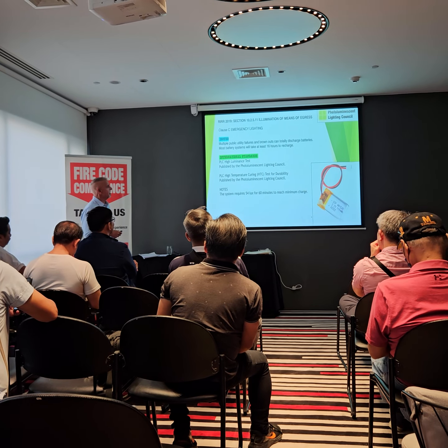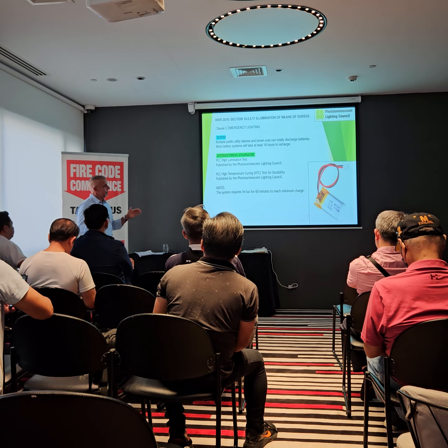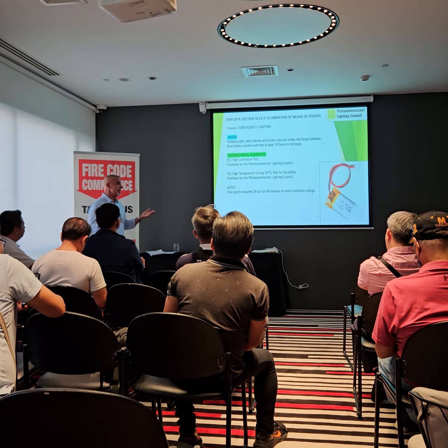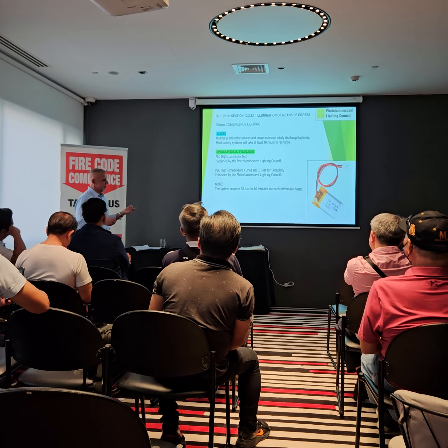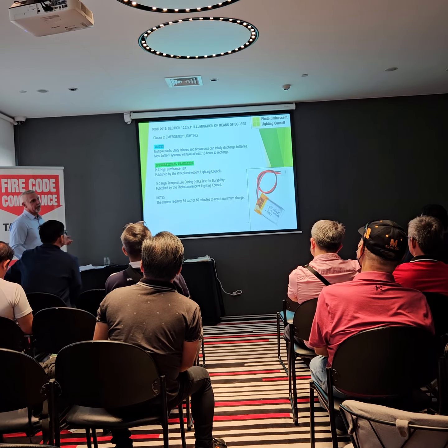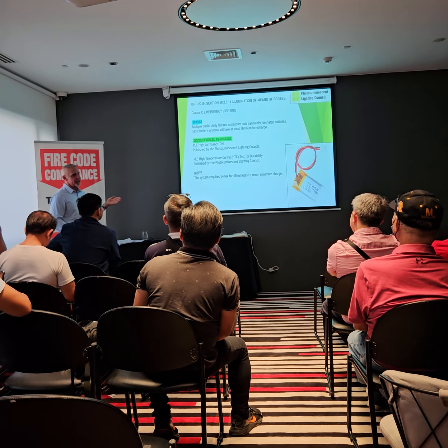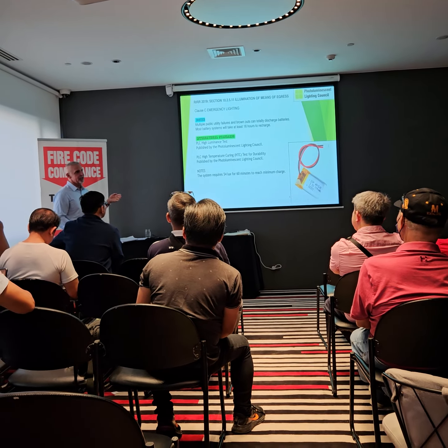Photoluminescent systems, if they've been totally drained, that means in total darkness for 3 days. That's how long it takes. Then it'll take 54 lux for 60 minutes. So as long as you are getting some light in there, you're going to recharge much, much faster.